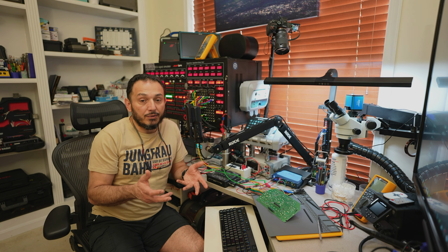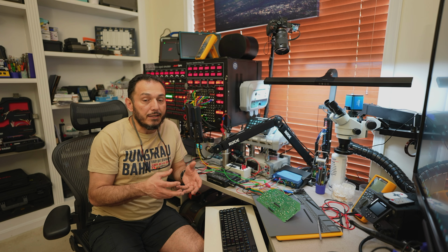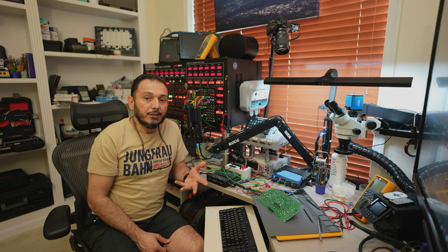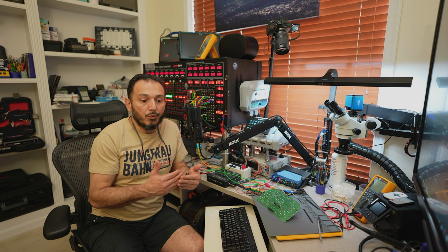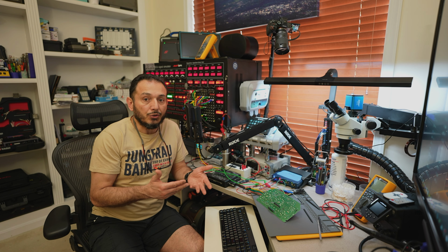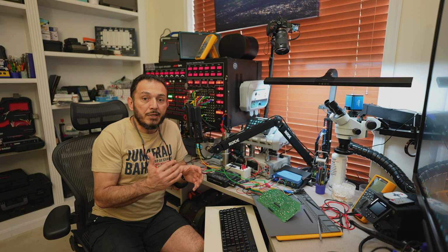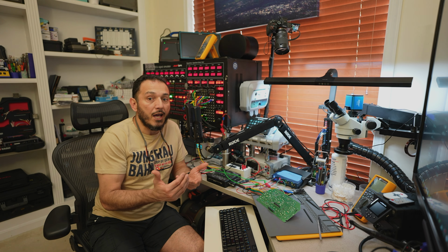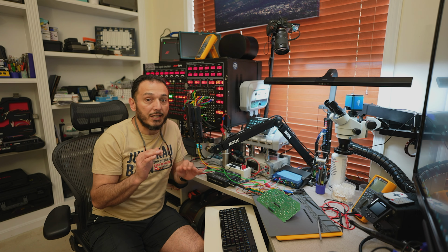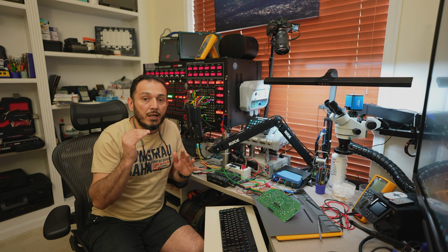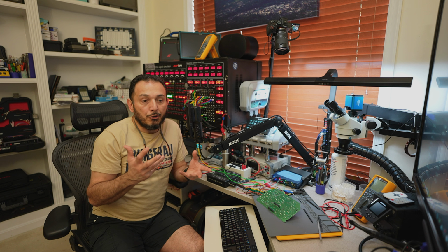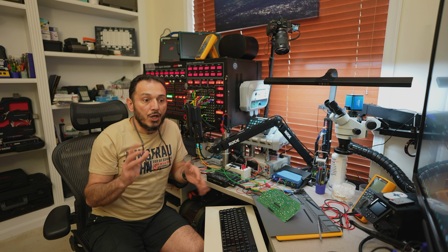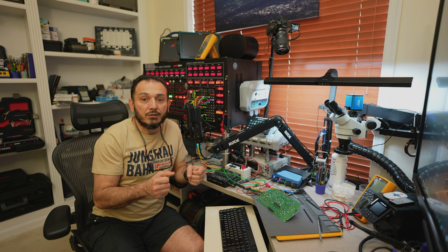And that is a very important signal because it's the speed signal to the ECM, to the radio, and other things in the car. Why is a speed signal going to the radio? Well, Toyota uses it to calculate the speed and then raise or lower the audio volume. So if you're going fast, they will raise it a little bit, so you will not even notice, but it will keep the same loudness depending on the speed. They're trying to do that to keep your hands on the steering wheel.